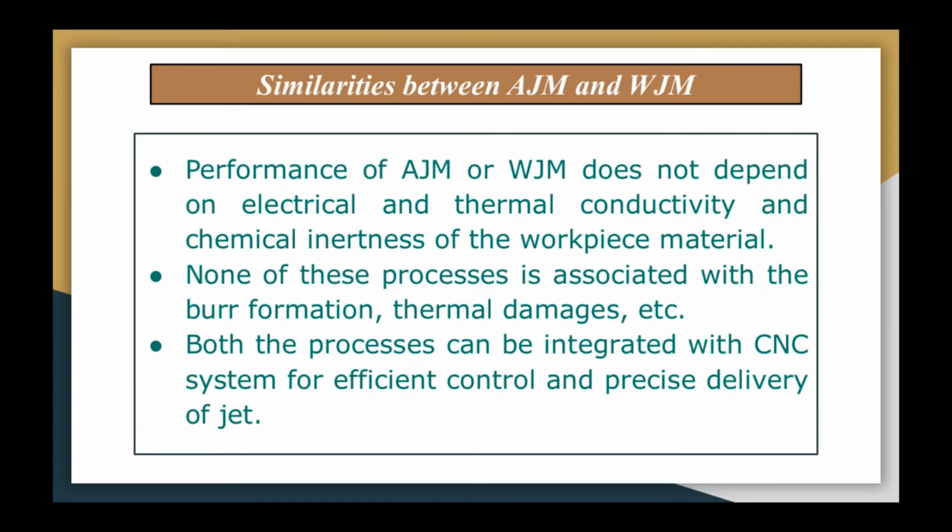Then the performance of AJM or WJM does not depend on the electrical and thermal conductivity and chemical inertness of the workpiece material. However, several mechanical properties like strength, hardness, etc. influence the process capabilities, and none of these processes is associated with burr formation and thermal damage.